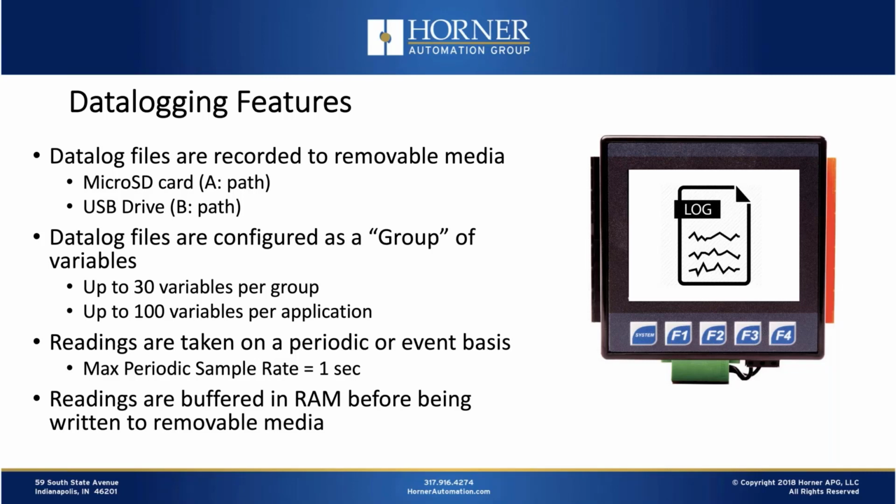Now, after readings are taken, especially those that are happening quite frequently, say every second or so, they're buffered into RAM prior to being written to removable media. Writing to RAM is a much quicker process than writing to removable media, which takes a little more time. So that's why we buffer them to RAM. Also, because we have a buffer, users can potentially swap out a card without losing any data, because the data is being buffered while the card is missing.